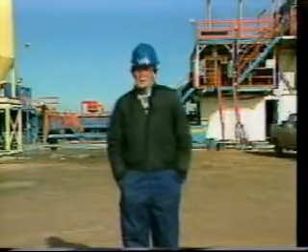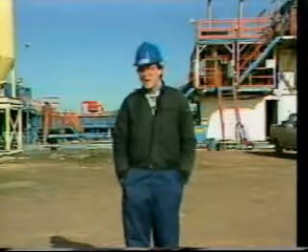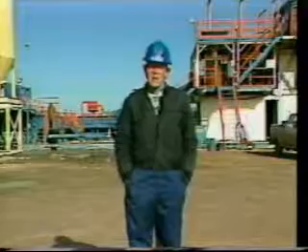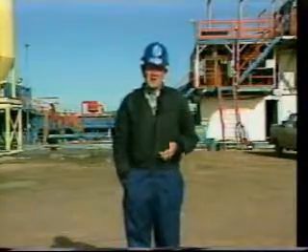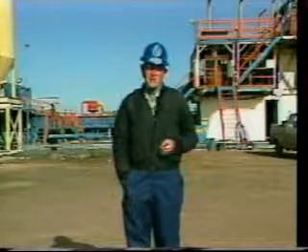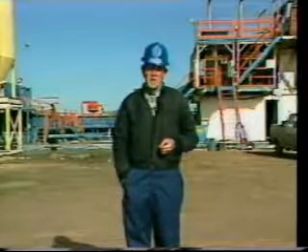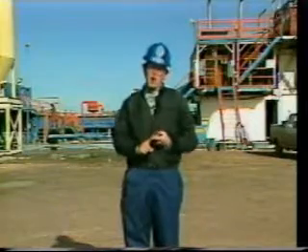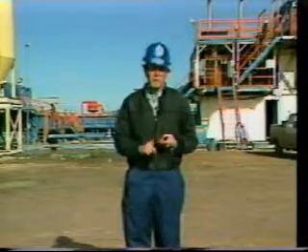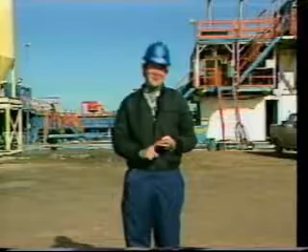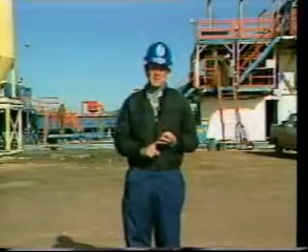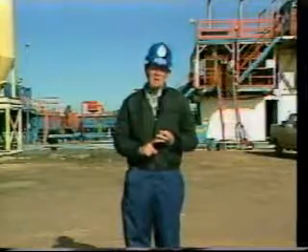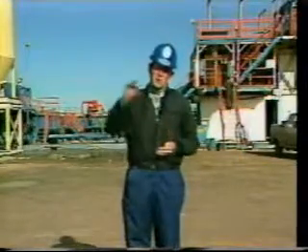Any offshore drilling can be difficult because of space limitations and the problems of transporting people and supplies in all kinds of weather. But drilling from floating drilling rigs, like a semi-submersible or a drill ship, has some unique problems, including maintaining position over the drilling location, providing a connection between the BOP stack and the drilling floor, operating a BOP stack on the seafloor, and compensating for the up and down movement of the drilling vessel.